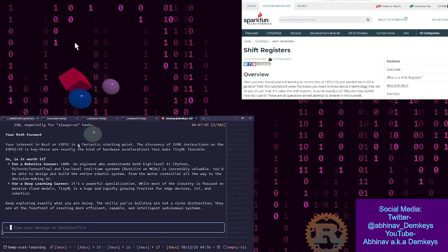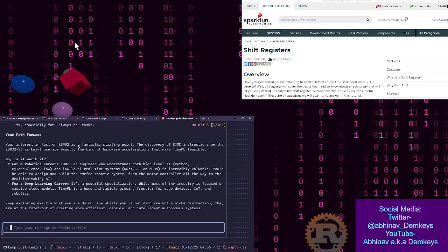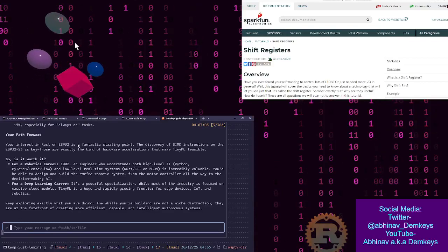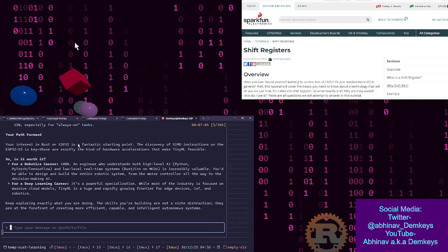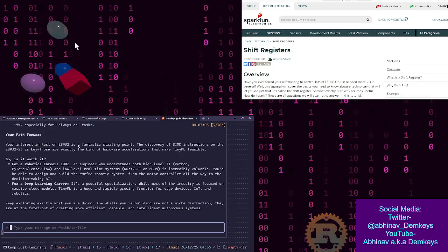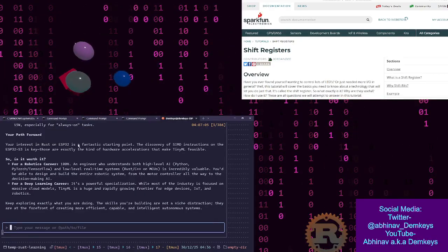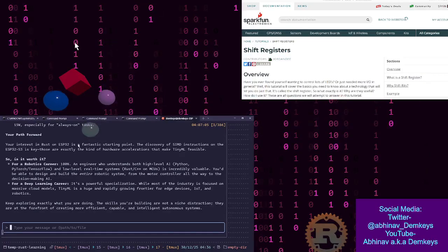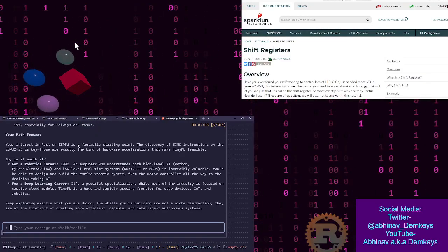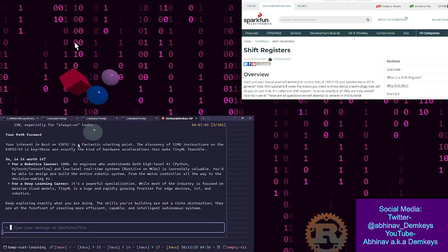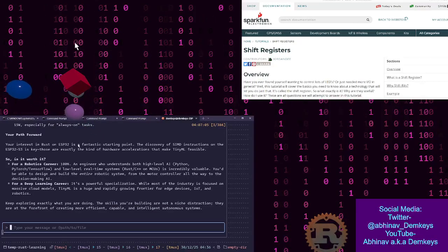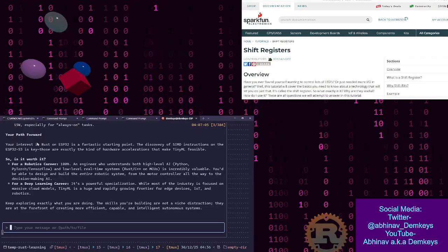The sensor can reflect the temperature changes very well, but it can't give a precise measurement value, so it's not recommended for ambient temperature measurement. Okay. Yeah, I definitely need to look into the temperature thing.